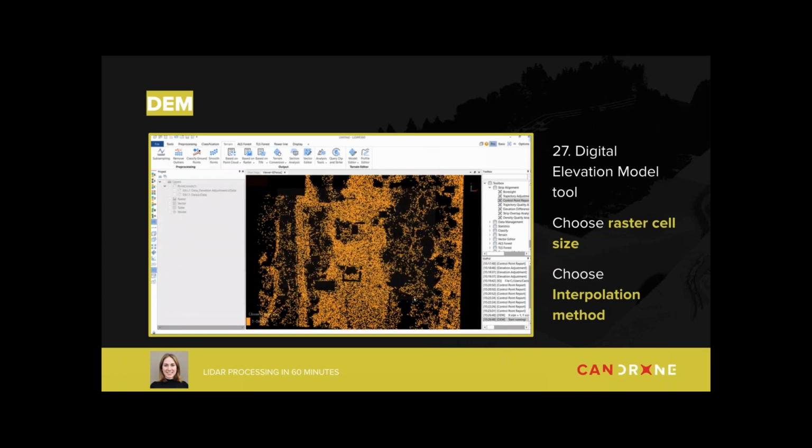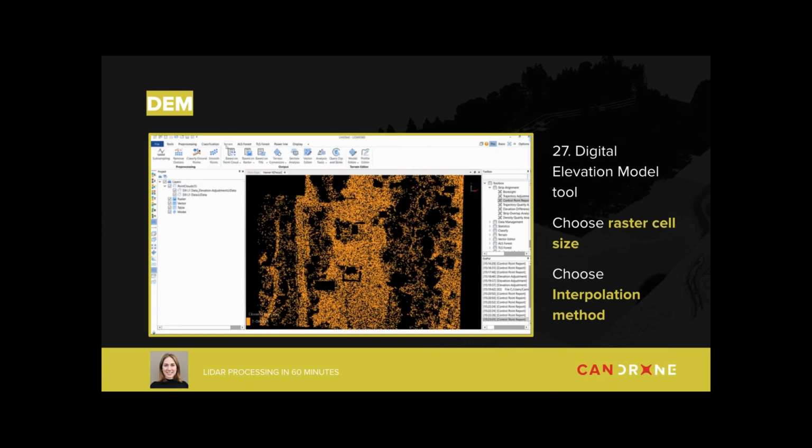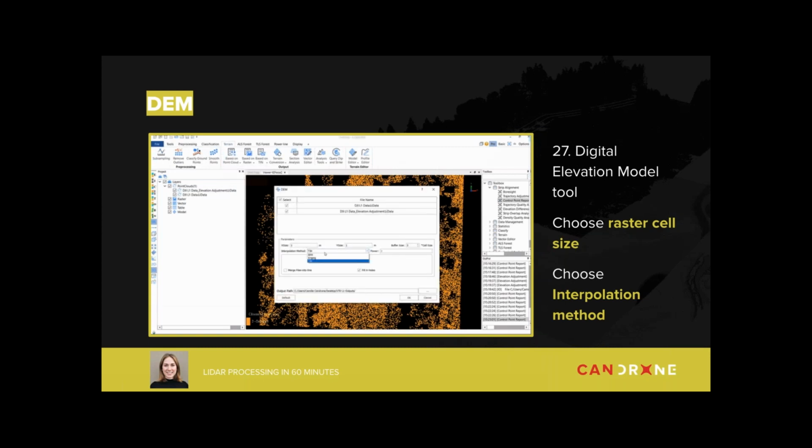Under the terrain module, what you want to do is select DEM and choose your raster cell size. For this example that you are seeing, we're making a 1 meter by 1 meter DEM. Then you want to choose your interpolation method. For this example, we chose TIN, which is a very common method, and then you can hit run.